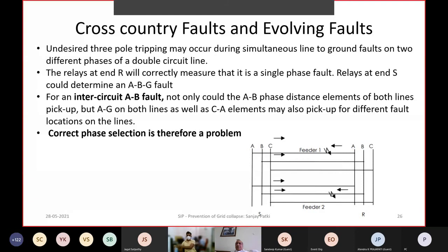That's why in some complex conditions, you may have, on a line, instead of distance protection, which is impedance based, a current differential relay as the preferred main protection, and you go for the impedance relay as backup protection.